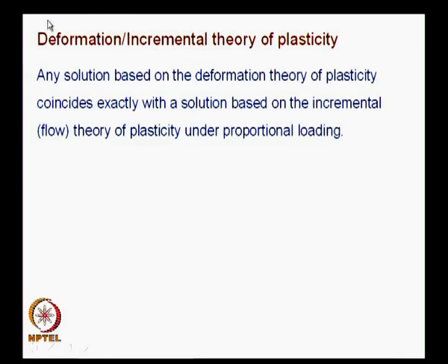The deformation theory of plasticity is easy to handle because the mathematics is far simpler, whereas in incremental theory of plasticity, the mathematics is very complex and highly involved. And what you find here is any solution based on the deformation theory of plasticity coincides exactly with the solution based on the incremental or flow theory of plasticity under proportional loading.